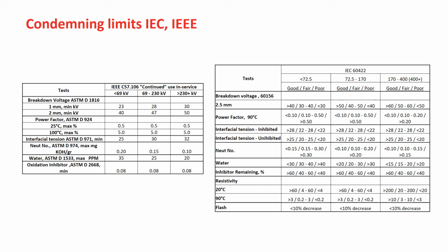The electric breakdown voltage, also called the electric strength, indicates the oil's ability to resist electrical breakdown at power frequency. This characteristic is measured in kilovolts by some standard test method and is one of the most important parameters characterizing an insulating liquid. However, it's very difficult to correlate its value with a given lifetime in service. This is essentially due to the fact that breakdown is associated with many parameters like water, gases in the oil,